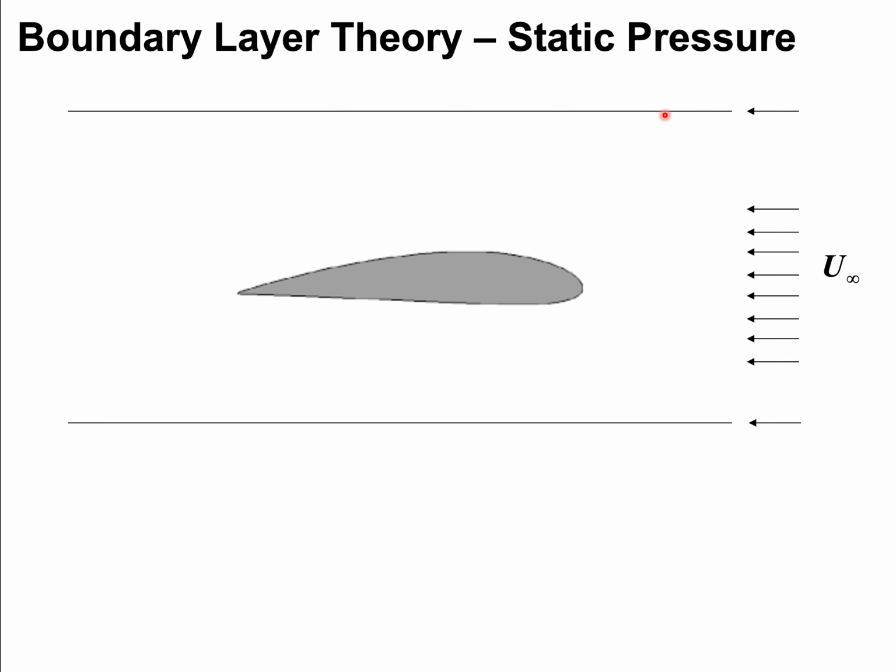And a flow path also signifies a streamline. And from our fluid mechanics study, a streamline can be treated from a mass flow perspective as a solid object. So here's now the story that we're going to build. This is a solid object, and there's a streamline here that behaves like a solid object because the definition of a streamline is that there's no flow that crosses it.